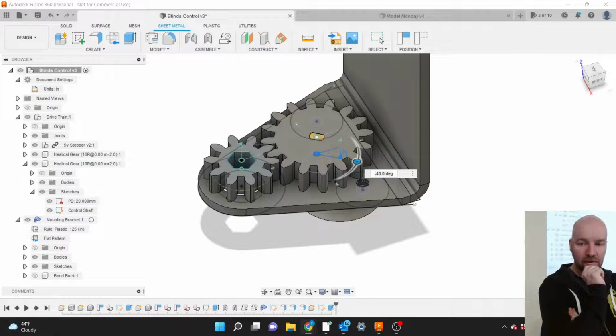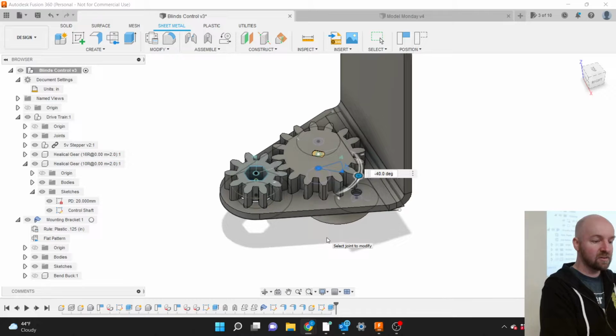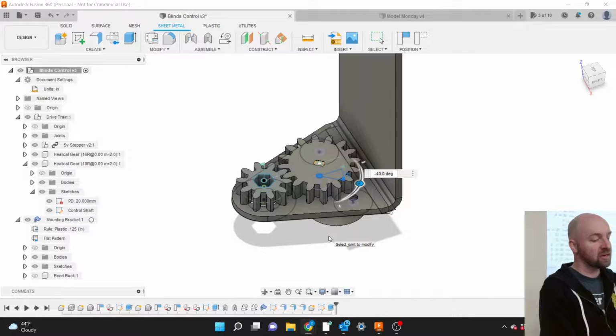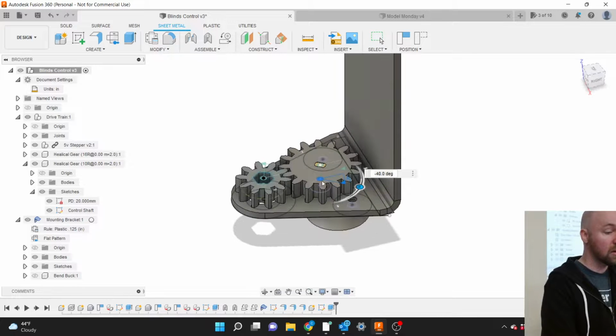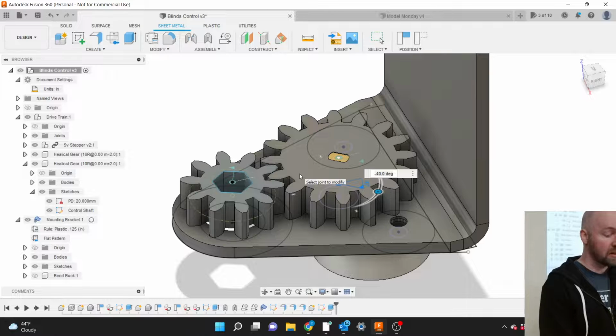When you made the two parts, which were like a mold to bend the plastic, is that the concept they would use for injection molding or die casting, where you draw whatever part you want and then you make the surrounding tool that would fit on it? Is that what they do? You could certainly use that, depends on your part. Like your gear, let's say it's going to be made out of plastic or injected aluminum. Could you make the mating parts of that, which would basically be the design of the mold?